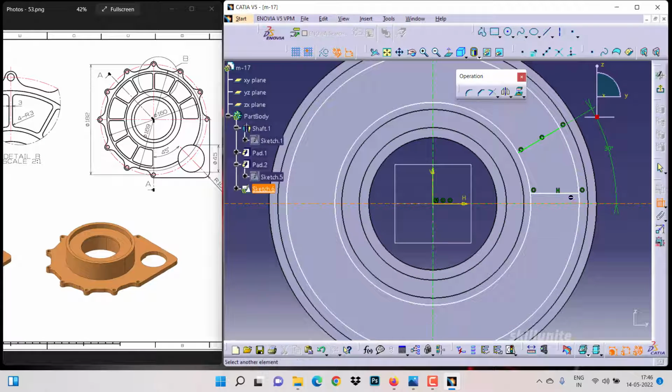So that means, consider this is going to be the center mark. This distance is going to be 1.5. Then next step, we have to focus on the circle, this one. So as you can notice, the circles whatever we are having also, it is just an offset of 3 mm.